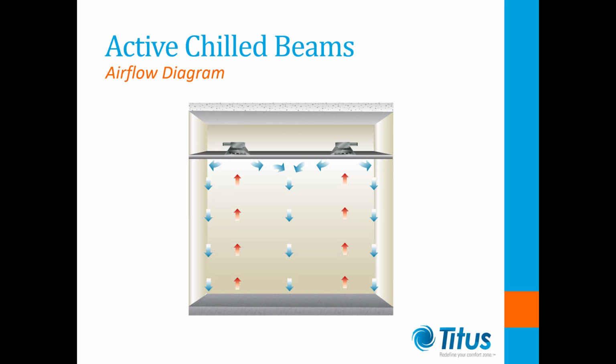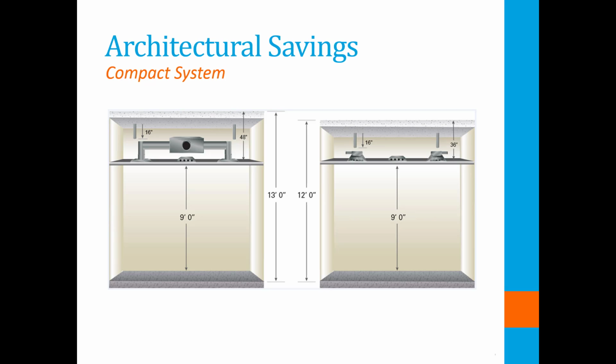Beams can be positioned above heat generating sources such as electrical equipment mounted on lab benches, so the rising warm air currents are captured directly into the induction grills of the chill beams. As most of the cooling energy is provided by the water system, less riser and interstitial space is required for the service ducts and pipework, resulting in a very compact HVAC system.